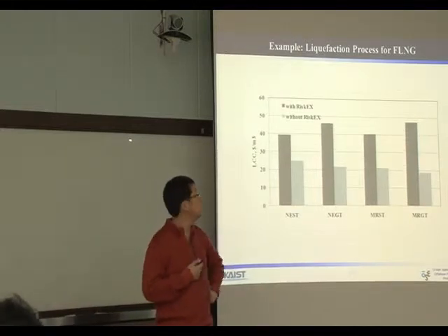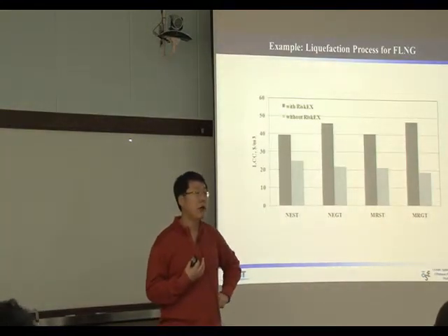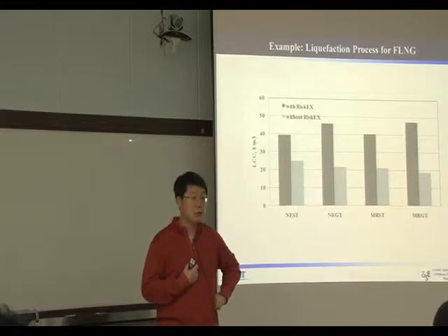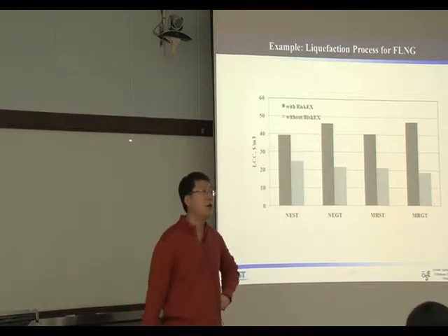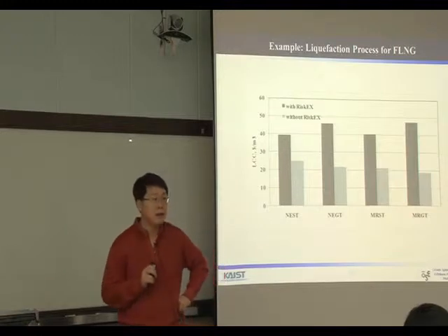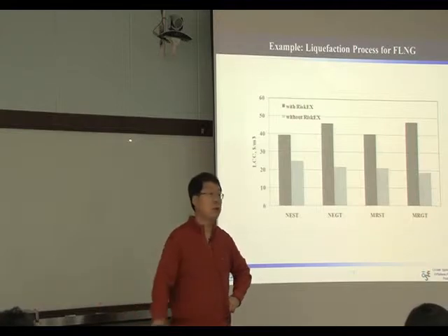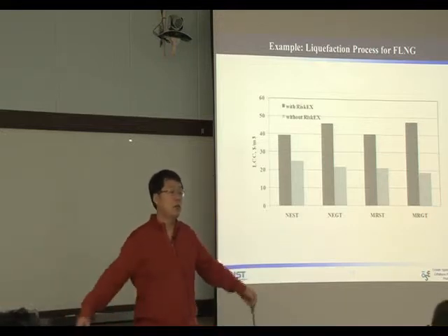But this is a question about risk and the money. Money is not everything in an offshore plant. What I mean is, in an offshore plant, the space is limited. So another big demerit of the nitrogen cycle is that it takes a larger footprint. Do you know the term footprint? Footprint is the space required for the facility.